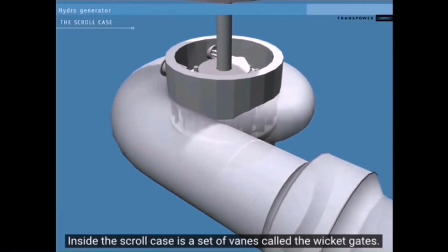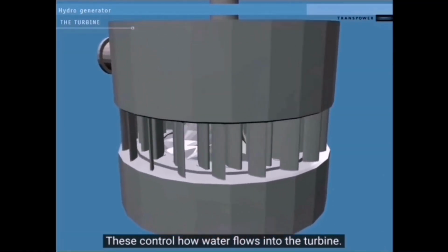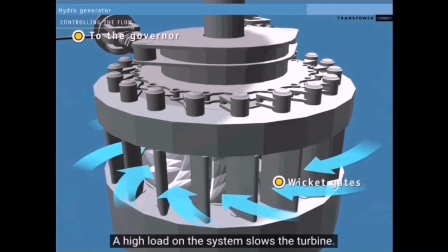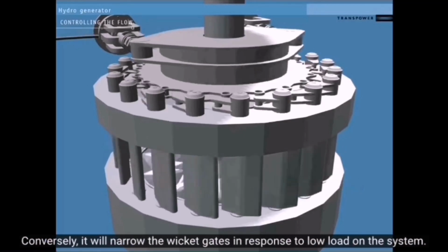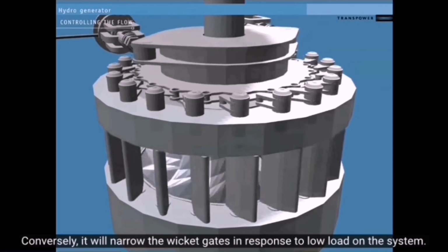There is a part inside the scroll case that we call wicket gates. These control how water flows into the turbine. The wicket gates are controlled by the external governor system. High load on the system slows the turbine, then the governor system reacts by opening the gates to speed it back up. To get a low load response, it will narrow the wicket gates.